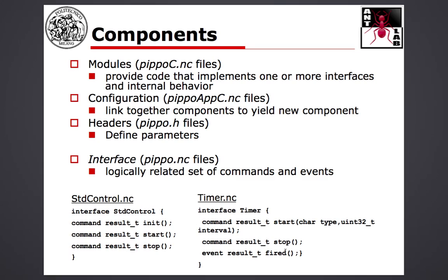So when the timer expires, we expect an event to be triggered from the timer component. So interfaces are instruction guides on how to use components, and they explain to the developer what kind of commands can be called on a particular component, what kind of actions can be made on it, and what kind of events that component may occasionally trigger, so asynchronous events or interrupts.